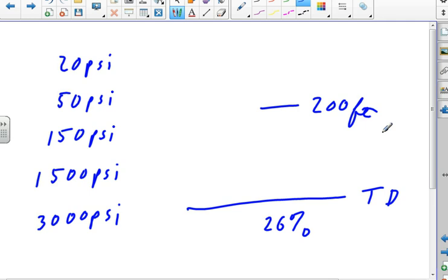But that meant that you had possibilities. Whenever you went down to test depth, you manned the phones in all the compartments. You rigged, you shut valves that were normally open so that the problems would go away in case they would never happen. And you'd have multiple people watching the depth gauge. You wouldn't just have one depth gauge being used. You'd have multiple people looking at the depth gauge.